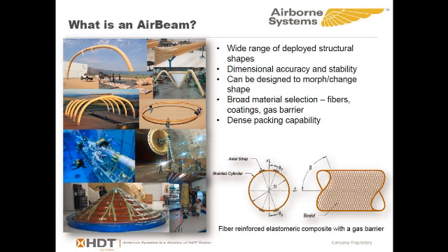And the picture at the bottom is the IRVE-3, which is a 3-meter diameter aeroshell that was launched last summer. And it was inflated in space, deployed and performed very well. It achieved Mach 10 and demonstrated that it met all the objectives.